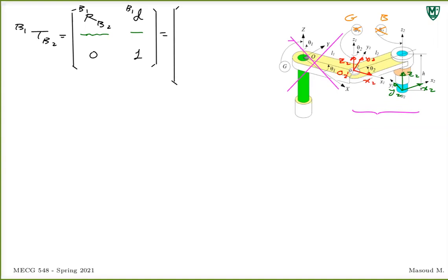You rotate in the positive direction theta 2, and then translate in the x direction L2. Yes, right. You go L2, but then down. But basically you have two translations, or one translation with two components. But you're right. So the general process here is what you do to get from red to green. So red, which is the body frame, is aligned with the global frame.